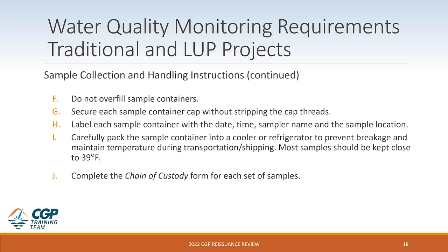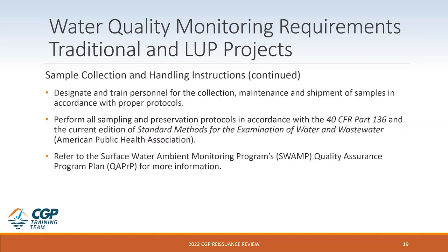Do not overfill the sample containers. Secure each sample container cap. Label each sample with the date, time, sampler name, and sampler location. You should always use a Sharpie for this so that it's water resistant. Carefully pack the sample container into the cooler and maintain the cooler temperature close to 39 degrees Fahrenheit. And always complete the chain of custody form and make sure that you keep a copy of that.